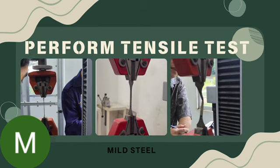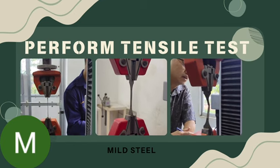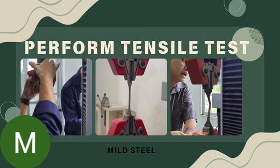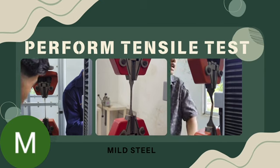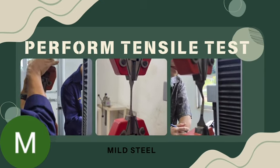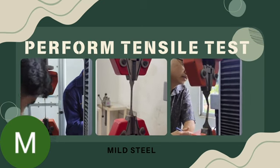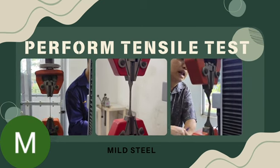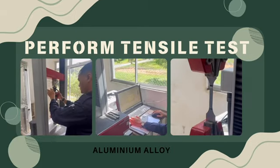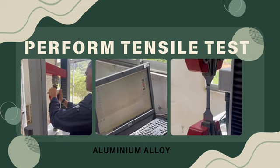For the next step, we have to perform a tensile test for both samples. Analyze the tensile profile, the stress-strain curve of the sample. We need to determine the percentage of elongation, percentage of area reduction, Young's modulus, yield strength, and ultimate tensile strength of the sample. Right now, we'll proceed and perform the tensile test on the aluminum alloy.